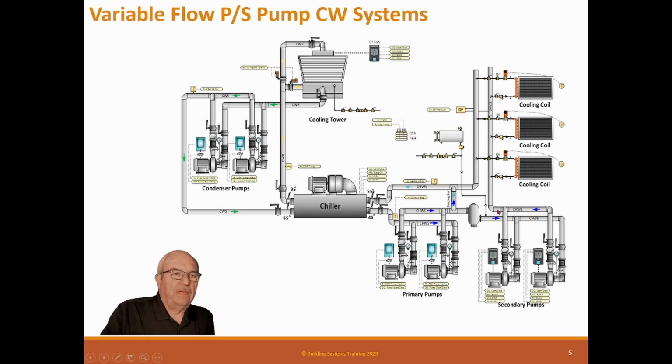Now, the reason it's variable flow, remember, this is a constant flow system, and this is a variable flow system. So these pumps can pump this water around like this, and if this has a bunch more water than this, then the water comes back down, and some of it goes through the decoupler in this direction, and this can run around like this. Okay, so it's possible for these pumps to actually have absolutely no flow, and this to actually operate that way.